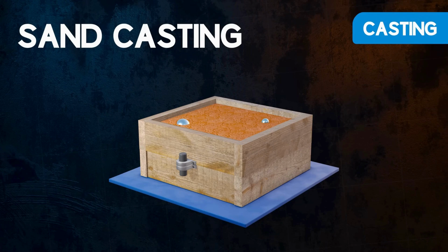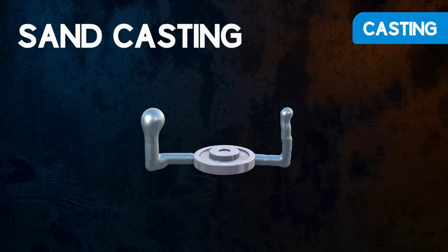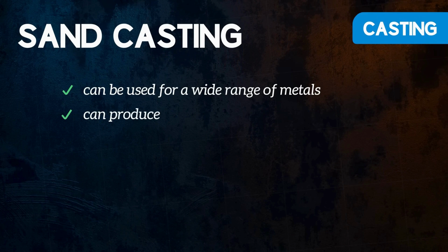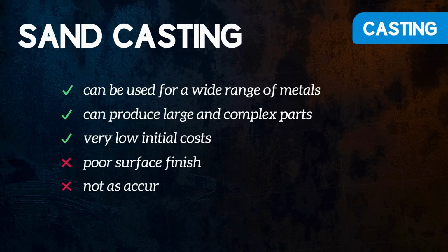When the metal has solidified, the cast object can be removed from the sand. Sand casting can be used for a wide range of metals, including those with high melting temperatures. It can produce large and complex parts, and initial costs are very low, making it good for small production runs. However, it provides a poor surface finish and is not as accurate as other casting processes.